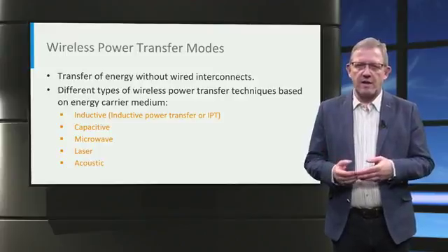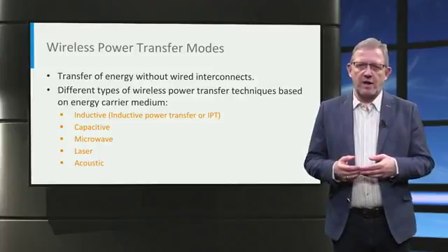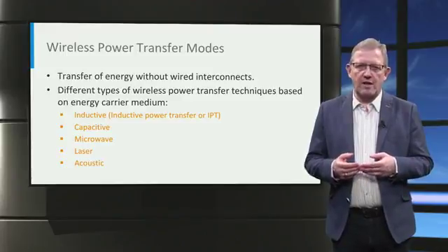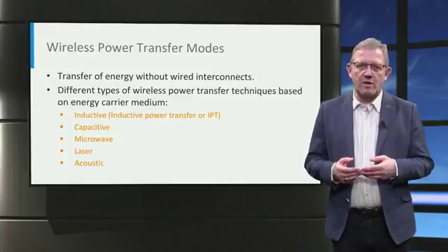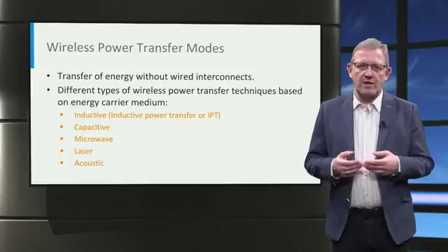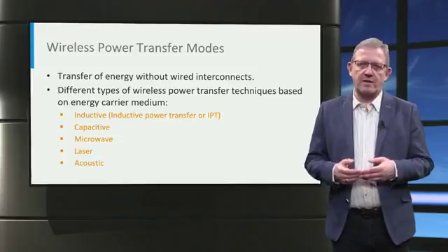On the other hand, capacitive power transfer relies on oscillating electric fields at frequencies of 100 kHz to MHz. Typically, applications involve low powers, 1 to 50 watts, with efficiencies in the range of 50 to 80%.